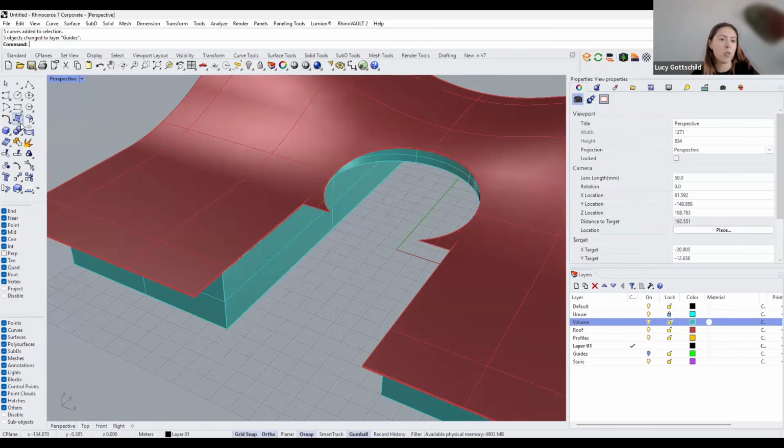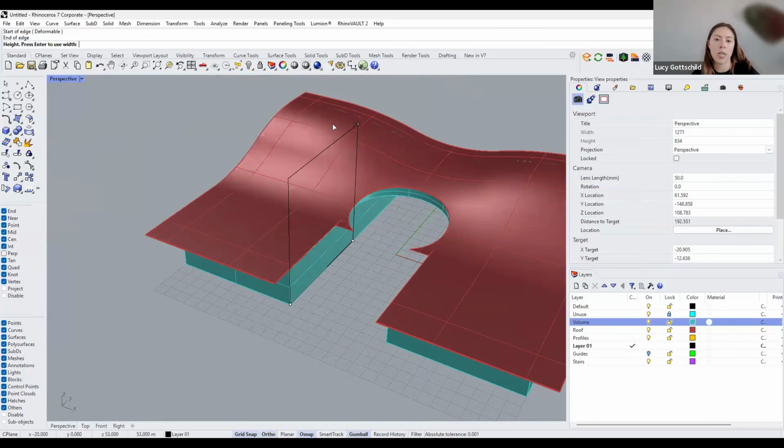And then here you have also a cascade for surface creation. So you click on there and you go down until you find the vertical plane. You click in there and then you will draw a vertical plane. So you will click where your plane wants to start and then click again where you want your plane to finish and then just drag it up.